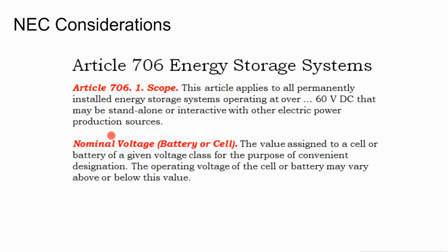When you go through a battery maintenance cycle where you're overcharging the battery to bust the barnacles off the top, you're charging it all the way up to its top rated voltage, maybe around 58 volts or so for a typical 48 volt battery bank.